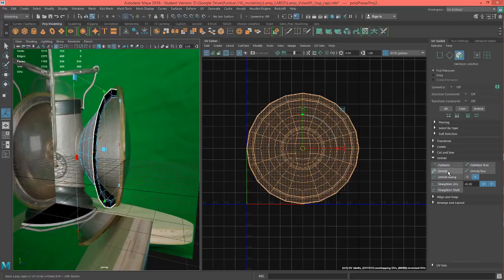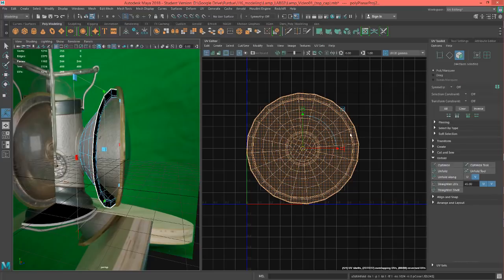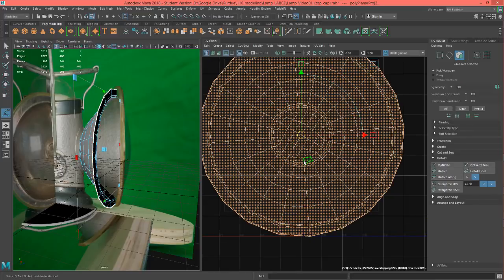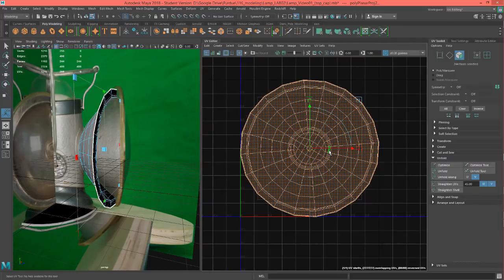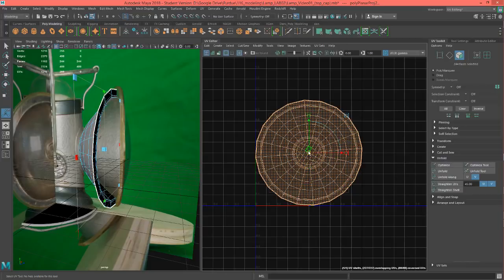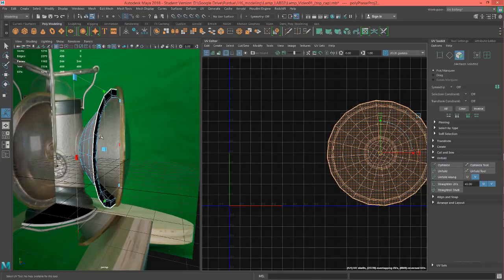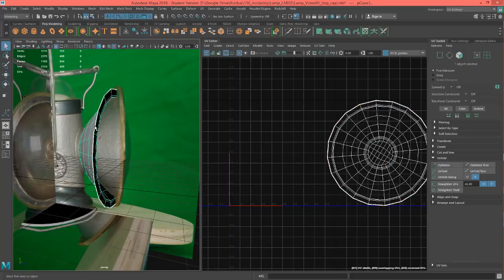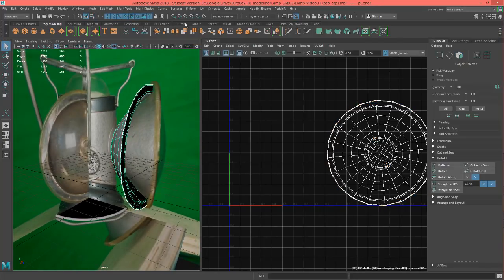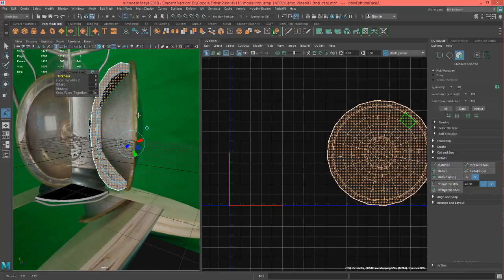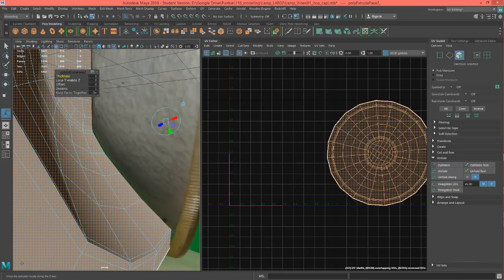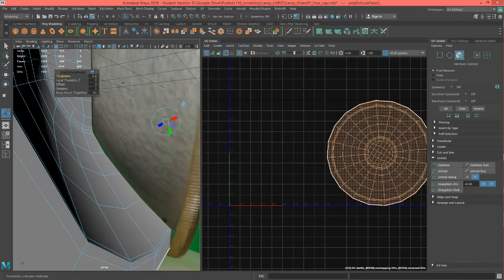all we have to do is close this out and do an unfold. In this case, I would probably do the 3D unfold because it does a really good job for shapes like this. And then we'll go ahead and just move this off to the side for right now. And then let's go ahead and do a thicken while we're right here. So we just hit extrude, and then I'm just going to do the thickness right here.